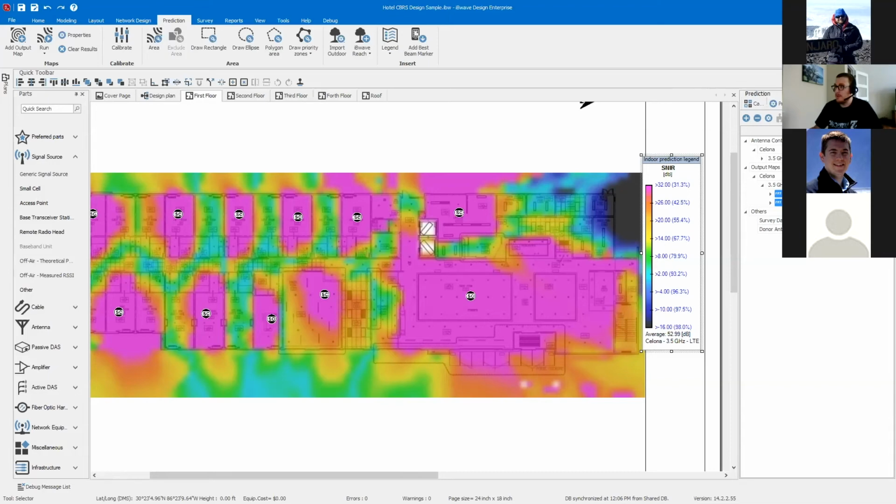I could activate the probe and actually see what is my SINR here. This is the area where I have bad SINR. So the ideal situation is to design so that this area is where nobody will be connecting. And you see between the rooms, we have bad SINR. Ideally, I would have 2 separate channels, so I would not have this bad SINR. So I have one channel here and a separate channel here, so I don't have this overlap here.